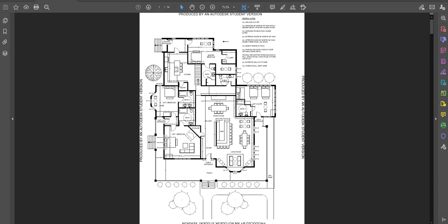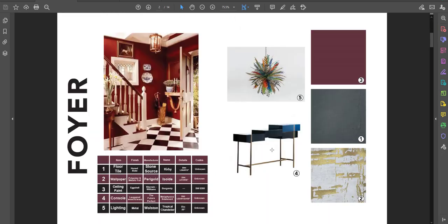Each room has been measured, right? We're showing the 5-foot turning radius. We're showing all of the window sizes, labeling the rooms, and so on. So your drafted floor plan will look something similar to this, of course, depending on your layout. And then each one of these will look a little bit different from different years and different requirements. But this gives you a sense of how students have approached it.